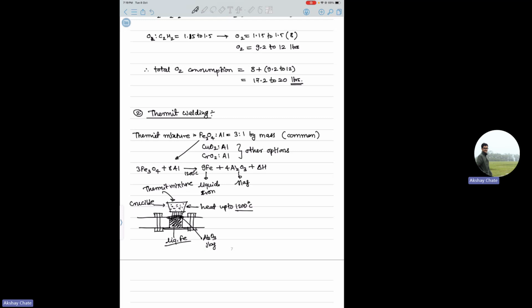The famous question that is asked is, first of all, what is thermit welding? And it has a peculiar application, which is repairing of railway tracks, because you cannot move railway tracks, and if they have some cracks, you have to do the welding or repairing there only. With this method, you take thermit where you want and do the melting there.